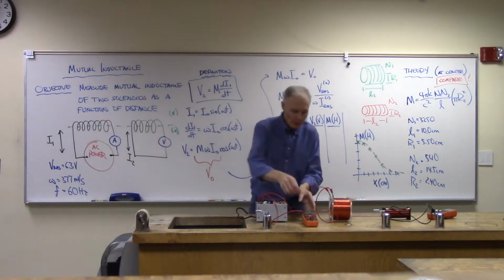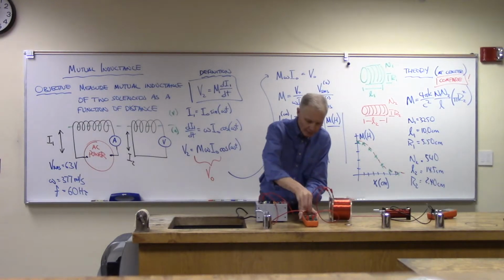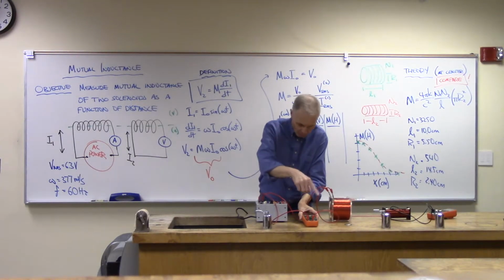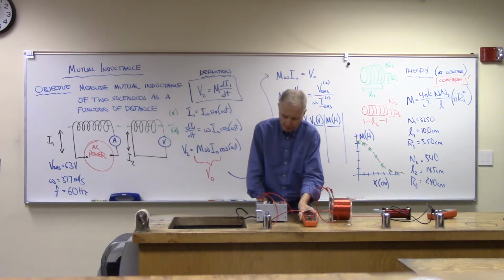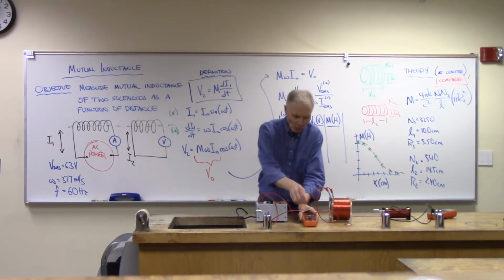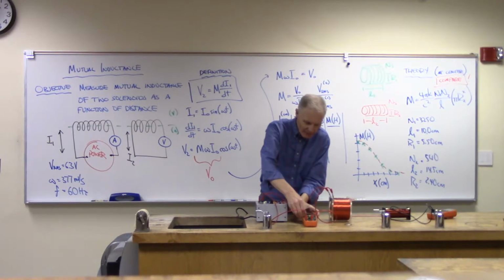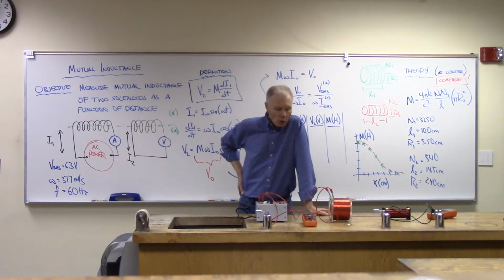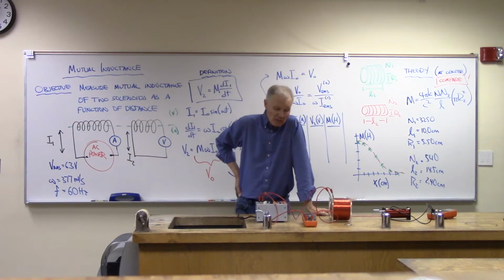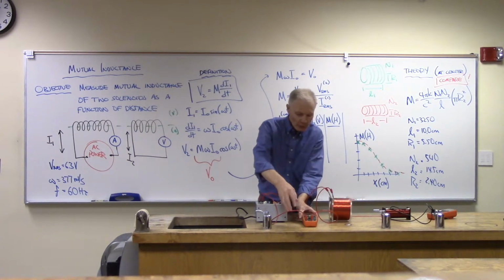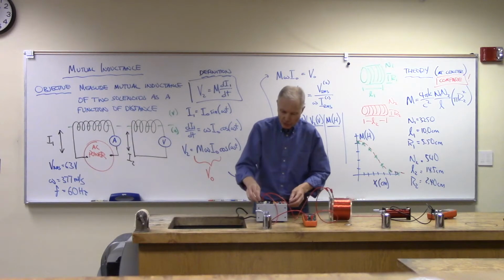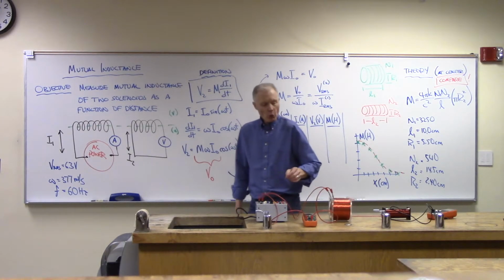And I guess I could do that now. I've wired everything, I believe it to be correct, and I'm going to turn this on, and it's got to measure AC. I always forget that last step. There we go. So I switched it over into AC, and I'm getting 23, 24, 25 millivolts, something like that. 23 millivolts it's reading. And so I'll turn this off.